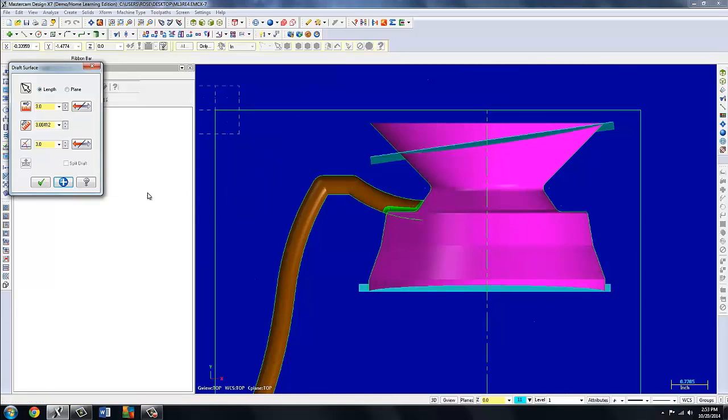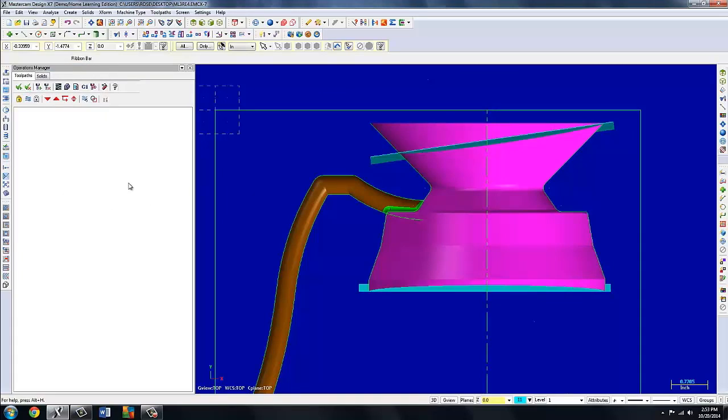Check out of that. I'm going to extend the revolved surfaces like we did in tutorial 4, just because I think they do that in case your subsequent fillets come out backwards. At least you can visually see that if you've got the extra distance to play with. Otherwise it may throw you something that you can't decipher as well visually. I'm just speculating on that, but it only takes a second to do it, so I'm going to do it. And ultimately it's going to be trimmed anyway once we get everything set correctly.